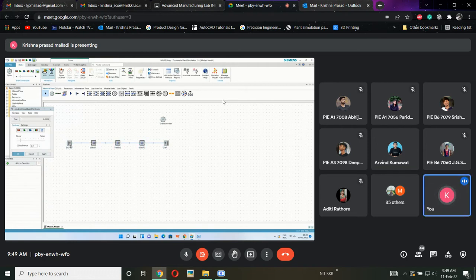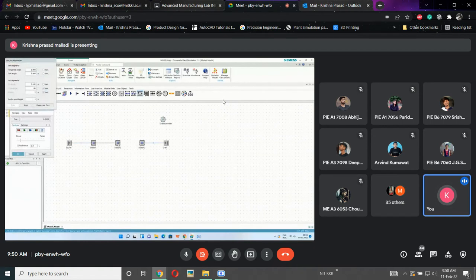It is just a representation for material movement. Now, in real life, if I want material handling, what do I need to use here? Conveyor. Yes, I don't want this one, I'm deleting it. I will be using this. This is what a conveyor will be, so that the material we are handling will be moved.